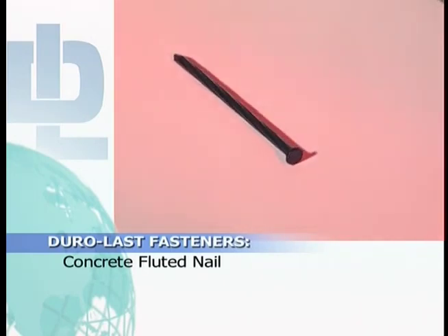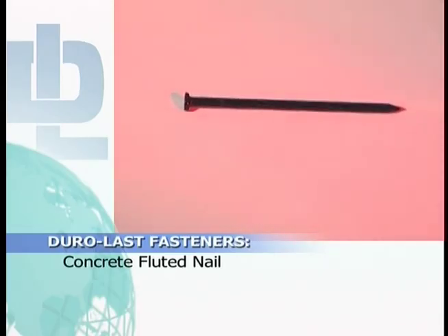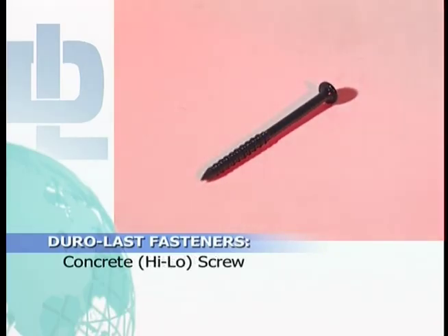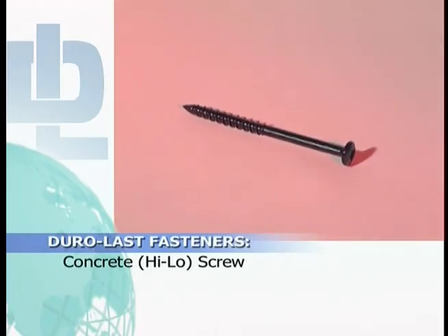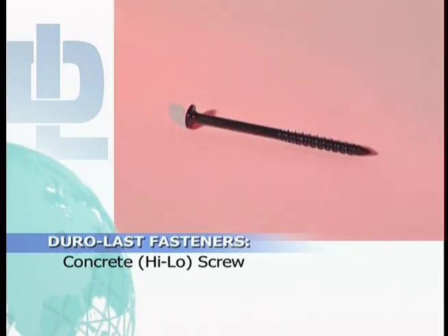If you must remove the fastener for any reason after driving it, you must cut the nail and discard it, then grind the stub down to the deck level. The Duro-Last concrete high-low screw is the recommended fastener for use on structural concrete decks.